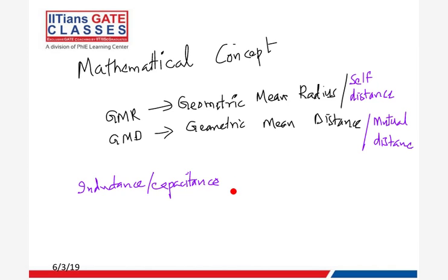So when we have a very composite or complex physical implementation of a transmission line, we need to deal with this mathematical concept also, right? This concept is only there for three phase three wire system, right? There is no GMD GMR for single phase system. Single phase one wire system, there is no issue. This whole issue comes only for three phase three wire system, right?